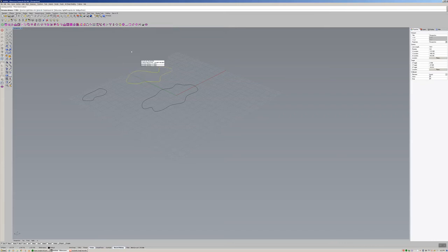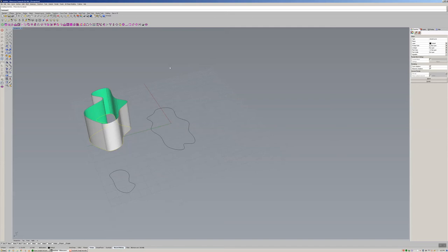And the reason being is I want to show you the second thing that 3D models are based off of, which is surfaces. Okay? So step number one is make a curve. Step number two is make a surface. Now if I make another surface and cover those two holes, now it's a solid. And what we call that is a watertight solid, meaning there's no holes and the thing is 100% sealed.